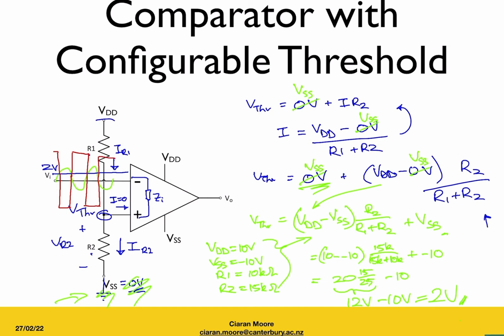It's worth just checking one more time that we've got that relationship round the right way. Remember, for an op-amp, our output voltage is given by our voltage gain, AV, multiplied by the difference between the voltages at our input terminals, in other words, the non-inverting voltage minus the inverting voltage.